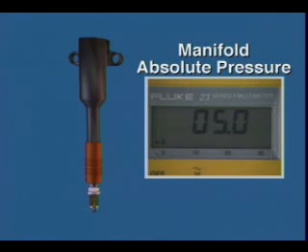The ECM commands multi-spark discharge based upon manifold pressure. When manifold pressure is increasing, the ECM commands the ICM to deliver multiple spark discharge until pressure at the MAP sensor is 7 psi or greater. As the manifold pressure increases, flame quenching is not an issue. There is more air-fuel mixture available to ignite, and higher cylinder pressures create higher cylinder temperatures. These conditions favor combustion. Also, higher cylinder pressures require higher voltages to arc the spark plug gap, which requires a high voltage or hotter spark.